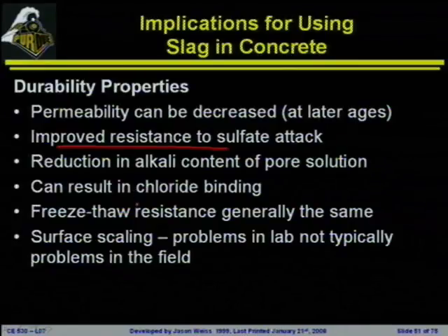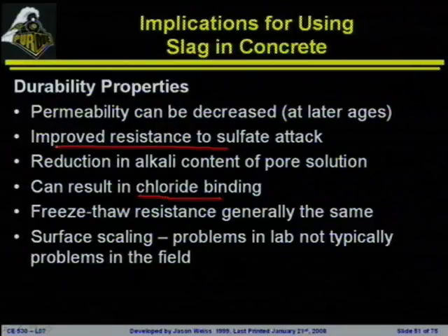You'll also see that slags can bind chlorides, so when we talk later on in the semester about salts, either from the ocean or salts coming in from deicers, they will tend to not only be slowed down as they go through the system, but the slag will want to grab onto them and hold onto them. So what you'll see is a lot of the chlorides will actually be bound before they can get to the reinforcing steel when you've got slag in the system. Freezing and thawing is generally very similar.